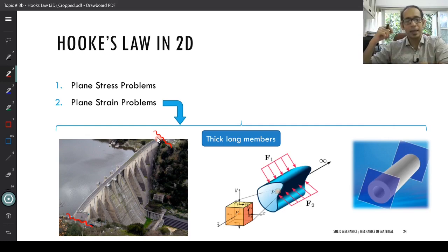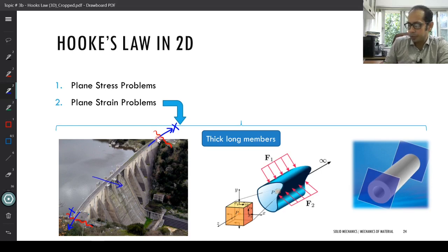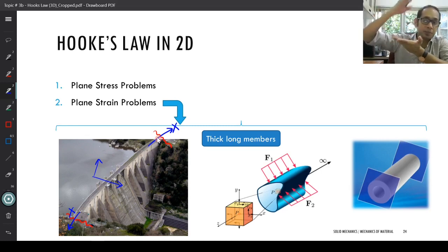The dam can have movement about the other directions, but essentially what you are doing is that you are restricting this movement as well as you are restricting this particular movement over here. The dam can still move about this particular direction and a vertically upward direction as well, right? It can have some amount of elongation, maybe due to temperature, due to the stresses of the water.